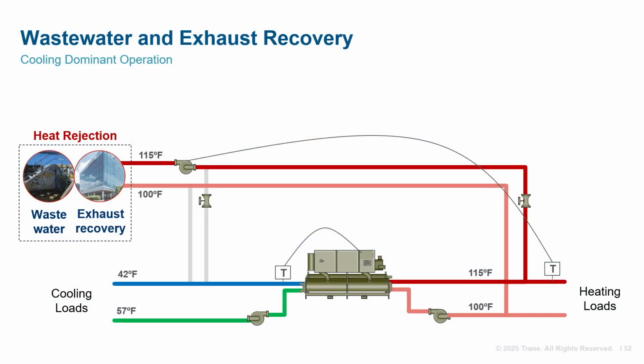Another option is to switch the control assignments for cooling dominant mode. Now the heat pump controls chilled water temperature and the heat rejection capacity maintains heating loop temperature. This is a more direct method of control and may improve temperature regulation. Not to mention that operators may find it more intuitive. The trade-off is that system sequences of operation get more complicated and the equipment must be capable of switching control modes.